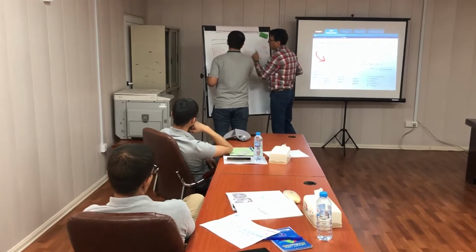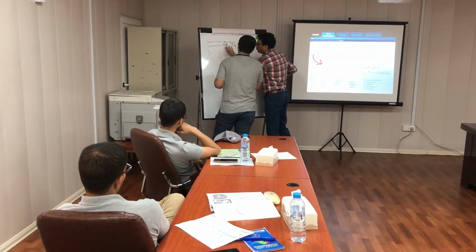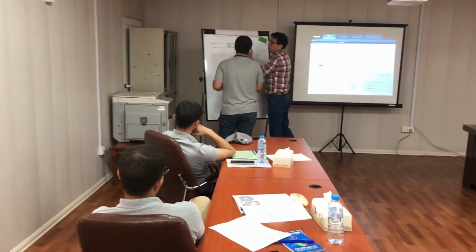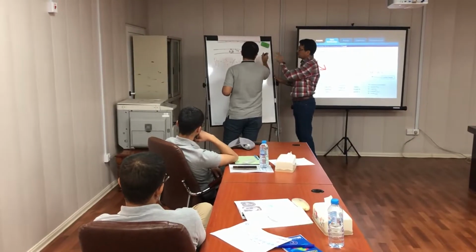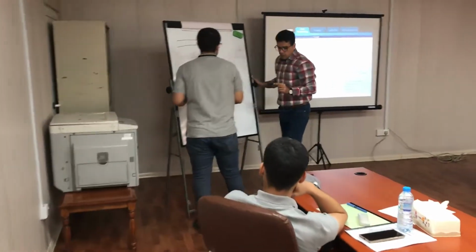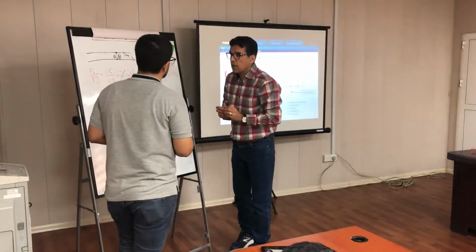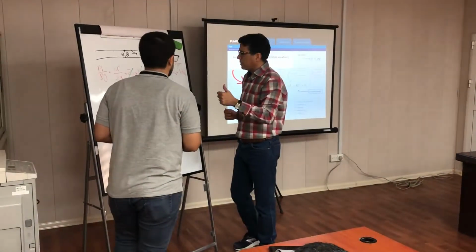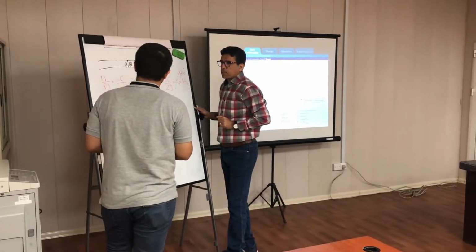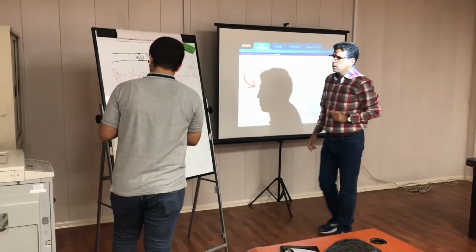Okay, we have a pump here in between. In this section, which part do you install a pump? We do not have a pump, and also no turbine. The friction, we have friction. This is like a 5 centimeter line. How can you calculate the friction for a 5 centimeter line? The pressure in the second section decreases. Write down the remaining parameters here. P1 over rho g.